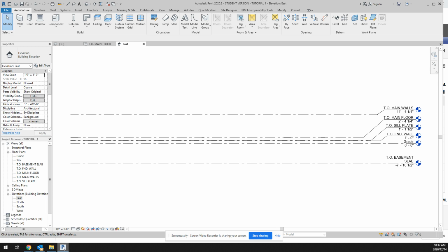All right, guys. So in Revit now, again, by this point, you should have your custom levels all created for your dream house. They should all be looking nice and clean on one of your elevations. So the east elevation is commonly the most used elevation for setting up all your levels.